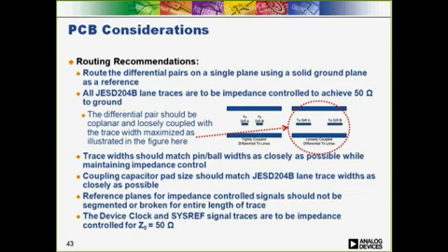Tightly coupled refers to differential pairs that have on the order of 2% crosstalk or more. A typical configuration considered tightly coupled would be a 5 mil trace width with 5 mil edge-to-edge spacing, whereas loosely coupled would be more like 5 mil traces with 15 mil edge-to-edge spacing. Loosely coupled refers to pairs that have very little crosstalk.